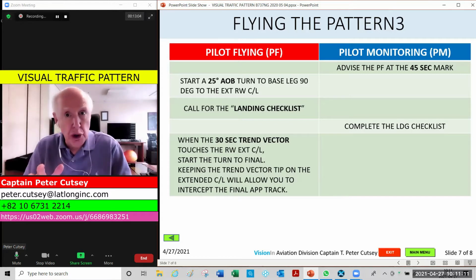Pilot flying, all you do is fly the airplane. Remember that pitch reference I gave you for 60 tons. You'll be very close to 6 degrees of pitch, very close. And try to use your flight path vector. We'll talk about that at some other time down the line once you understand how the flight path vector works. The exercise today is mainly using the aircraft boresight or the symbol and placing it where you want it, trimming off the forces, and maintaining your altitude and your speed. Good exercise.